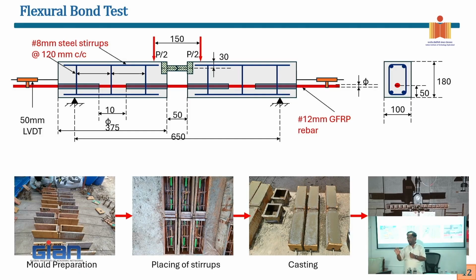No, this is right after cracking. Right after cracking, the neutral axis has gone up, at higher service moments. That's what I said: the lower bound is IG, I cracked, and then I effective will be in between them. Then sir, if that happens, then ICR should be more than I effective, because it is just incipient. No. This is at higher levels after cracking, in the post-cracking regime.